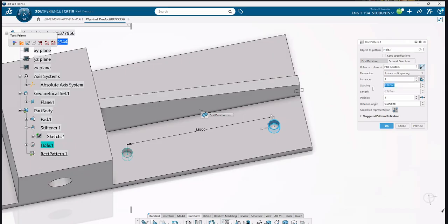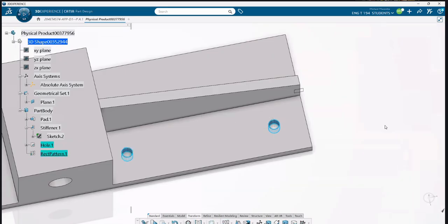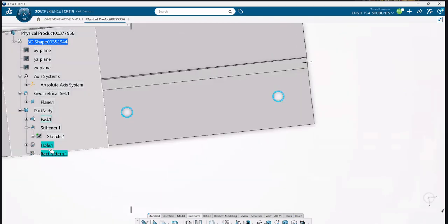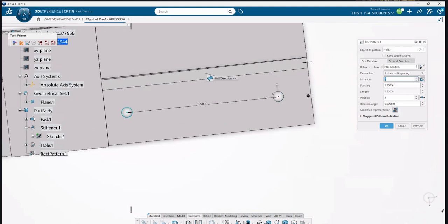And then my spacing would be then what? 1.5. 1.5, right? Because it's 3 minus 0.75 times 2. Yep. Would that be the right formula? I'm going to hit tab and C and select OK. Oh, David. You didn't change the number of holes. Luckily, all I have to do is double click the pattern in the tree. Under second, I have 1 instance. I got to go 2 instance. Do I have 3 there? Okay.